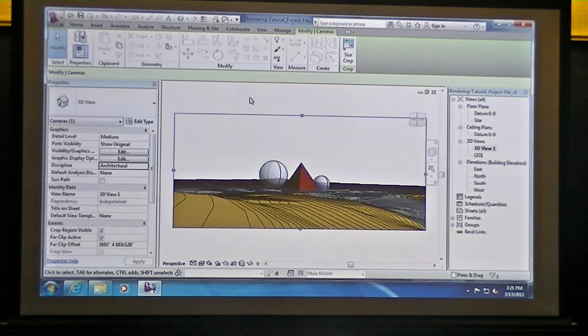You might have a very large image, you might have some smaller images that showcase your work. You don't want to render everything at 24 inches by 36, because then you're sitting here wasting about an hour or two on each rendering when you could have been rendering something more like 6 inches by 10 inches, which is how you plan to use it on your presentation board.